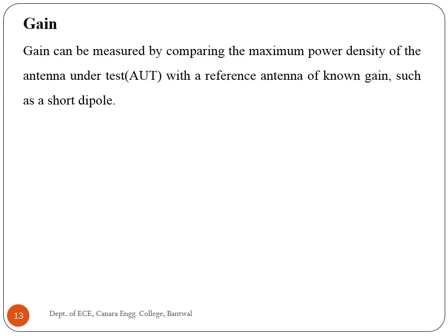The gain of an antenna is an actual or realized quantity which is less than the directivity due to ohmic losses in the antenna. In transmitting, these losses involve power fed to the antenna which is not radiated but heats the antenna structure. A mismatch in feeding the antenna can also reduce the gain. The ratio of the gain to the directivity is the antenna efficiency factor.